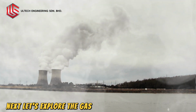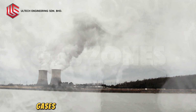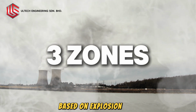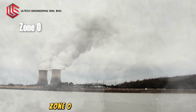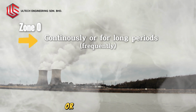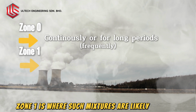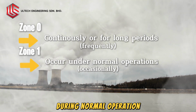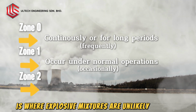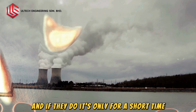Next, let's explore the gas zones for combustible gases. In industrial environments, gases are classified into 3 zones based on explosion risk. Zone 0 is where explosive gas-air mixtures are present continuously or for long periods. Zone 1 is where such mixtures are likely to occur during normal operation. Zone 2 is where explosive mixtures are unlikely to occur, and if they do, it's only for a short time.